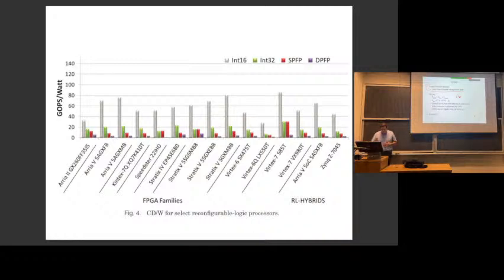So that's good. You also get a little bit of a drop usually in voltage. Less than we once got because we can't drop the voltage as aggressively as we used to because we're getting just too close to the threshold voltage. And as you approach the threshold voltage, your transistors are no longer turning on and off. But we're still able to drop the voltage some, which also reduces power.